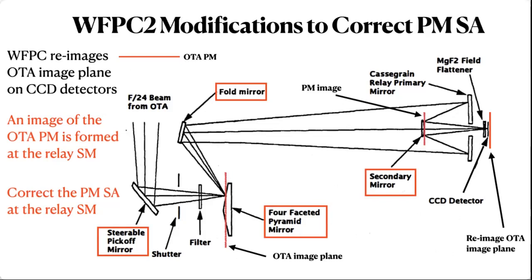of engineering challenges. The first thing that becomes apparent is the image of the primary mirror has to be very well registered with the correction on this secondary. So think of it this way. Imagine you have 2 bowls that are nested. If their axes are in line, then the 2 bowls fit together nicely. However, if you decenter or displace one of them, they not only don't fit together, but one of them starts tipping, and you get problems. And that's the same thing here. If the image of the primary mirror is not well registered with this mirror, you end up with worse optical problems than you started with. That alignment was determined to be about a few microns.